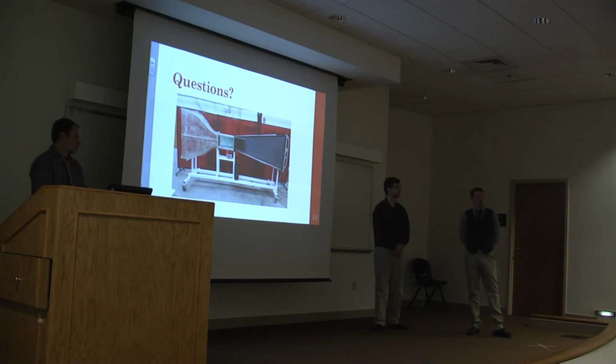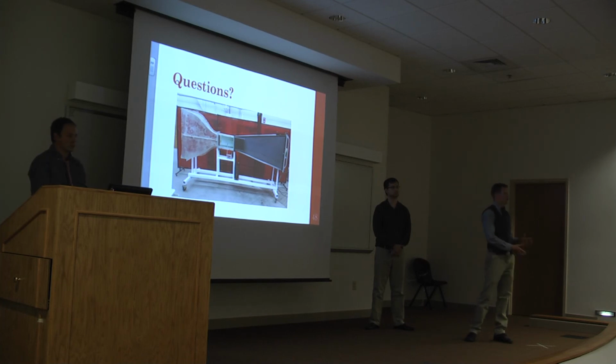It should be. For the MATLAB code, we wanted a 1% turbulent intensity, and that's the max. So at 130 miles an hour, we wanted that turbulent intensity to be at 1%. So anything below that should be good. We just use that 130 miles per hour to size the load cells. At 130 miles an hour, you're going to get a lot more lift force than you would at 60 miles an hour. So those load cells have to be able to handle the maximum force that would be seen inside the test section.